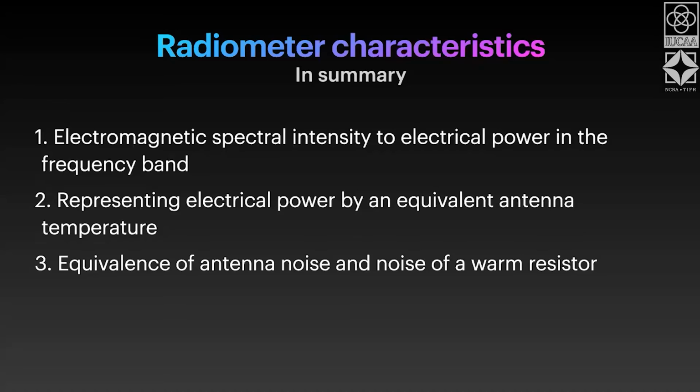That is done by setting L much larger than the wavelength of interest, so that the graininess in frequency is very tiny. So you practically have a continuum, but you have the advantage of estimation using the discreteness.